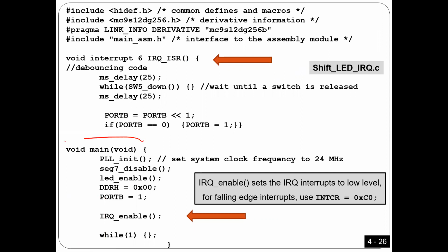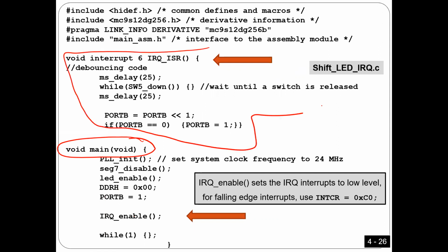This is the main program, right? So you have a main program here. Also, this is the interrupt subroutine program. In the interrupt subroutine program, guys, you should put here void. You should put here the word interrupt. So the word interrupt here is a keyword, right? And then you put here a name. Here it can be any name.